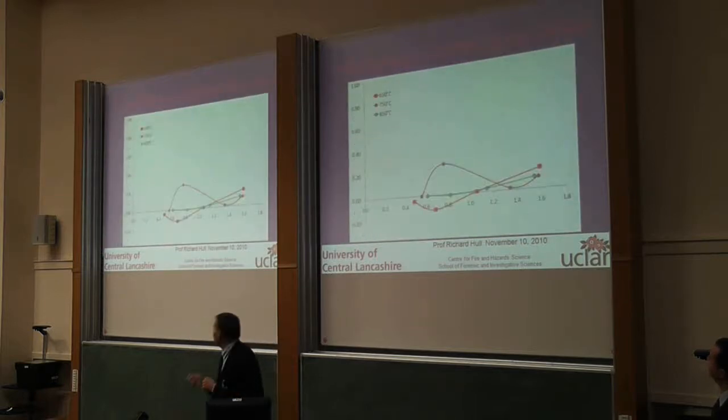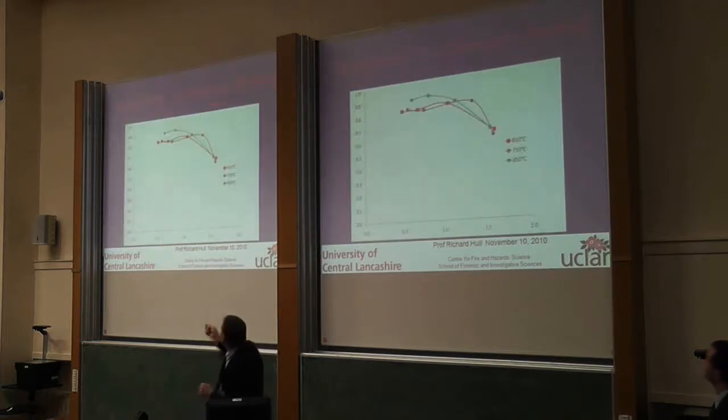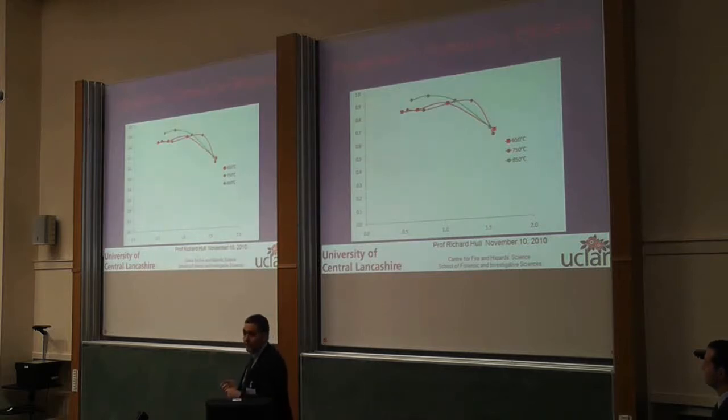Okay, and then we can actually do the same thing in terms of hydrocarbon yield, that we're getting lower yields of hydrocarbons at low temperatures, and then as the equivalence ratio goes up, independent of the temperature, we're getting a higher hydrocarbon product, so we lose complete combustion. Combustion efficiency obviously falls away as we reduce the amount of oxygen that's available.